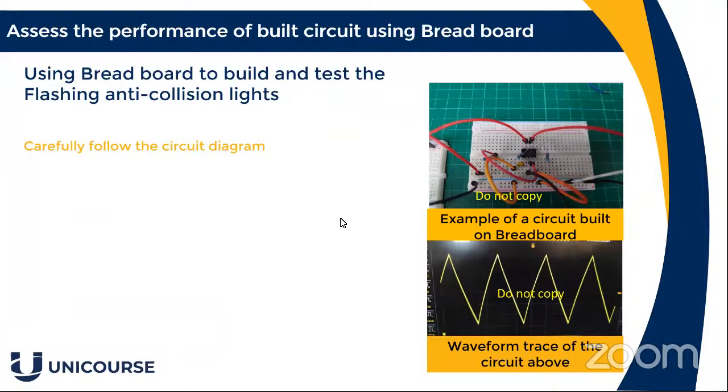Now, back to the actual breadboard building. If you are working on the higher grade, there are some hints and tips, which we will cover a bit later on within this presentation. What you want to make sure is that you've got a nice clear view of the actual circuit built on breadboard. You want to ensure that the wires are neatly connected up. What I would do is connect it all together and make sure it works. Once you know it's working, then cut each wire and neatly put it in. It's a bit messy, but it's not bad.